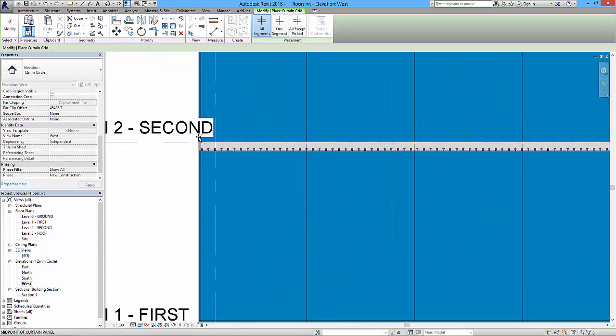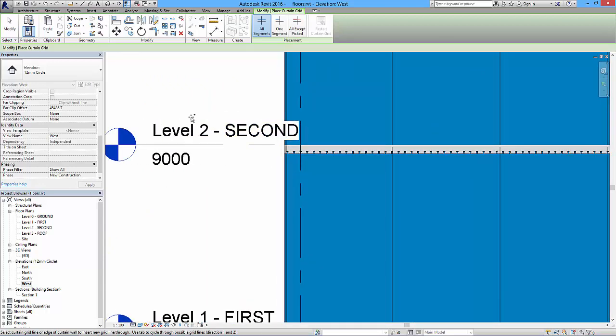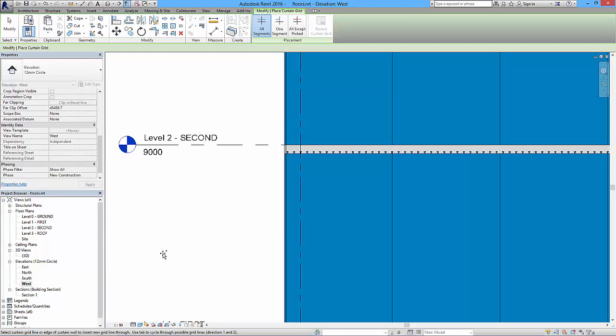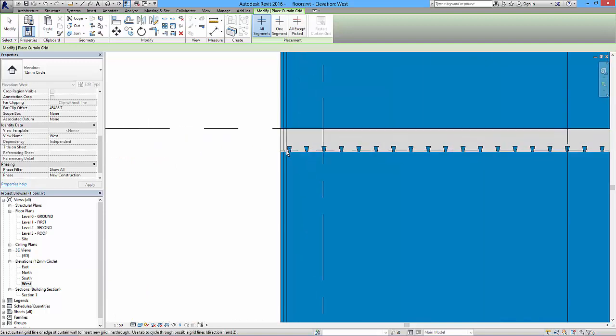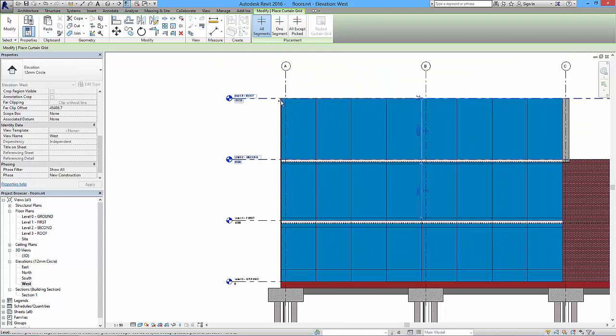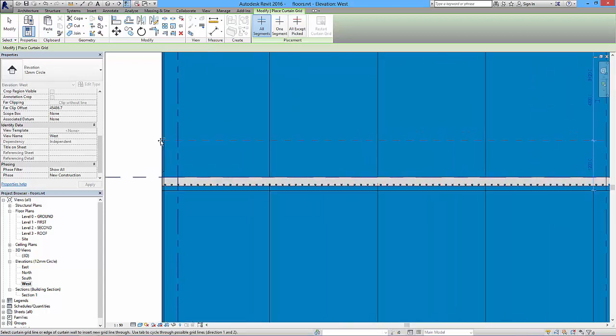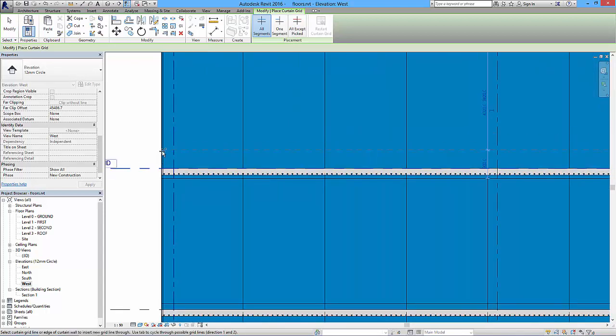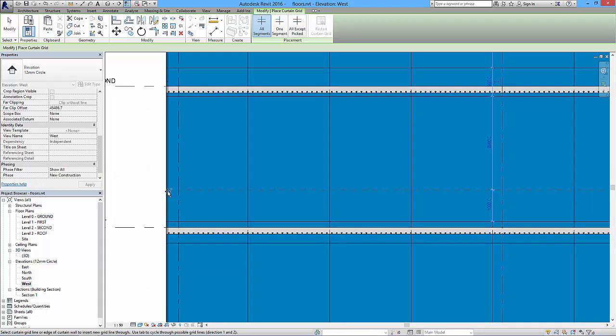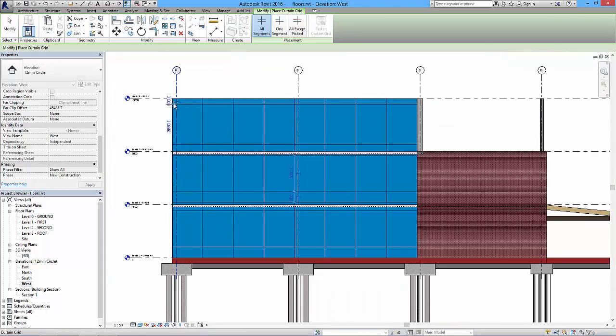And if I come in at this point now, this is sitting over that, so instead of just dragging these things out, I'll change the scale from there to 1 to 50. That'll just reduce that down, so I can come in and pop these in like so. So all I'm doing at the moment is putting a grid in, and I could also have that in so that that's looking at about 900mm up. There you go, and another one 900mm. So that's given us a grid system on this face.